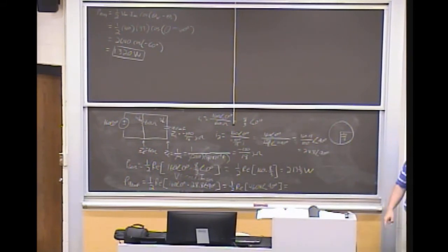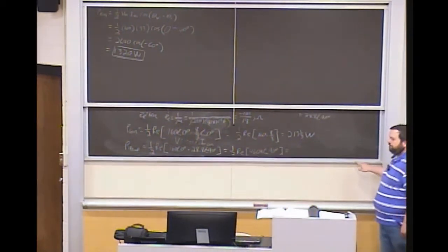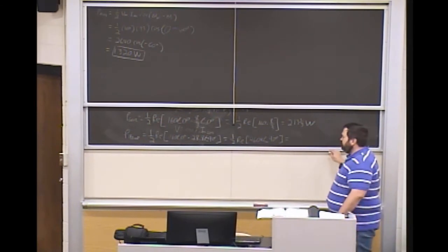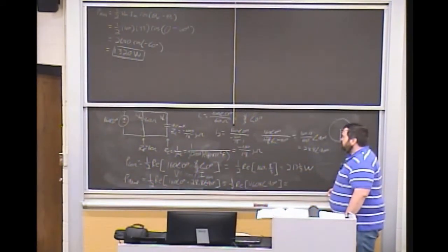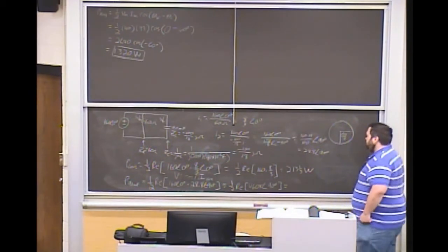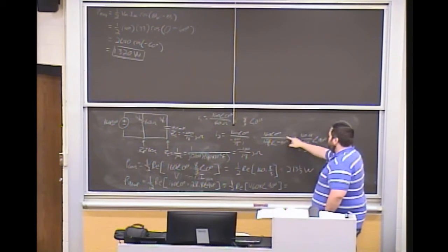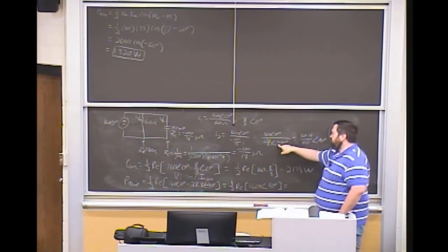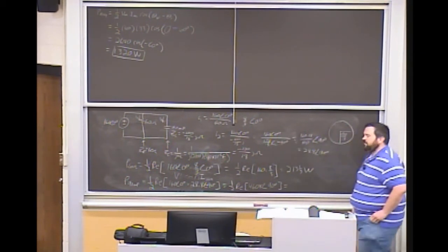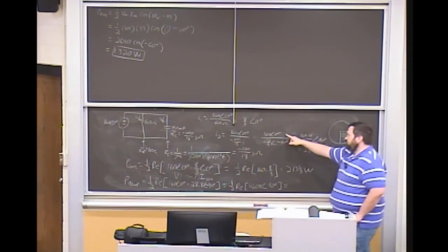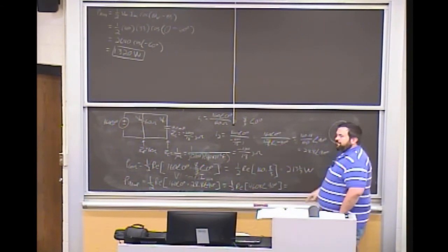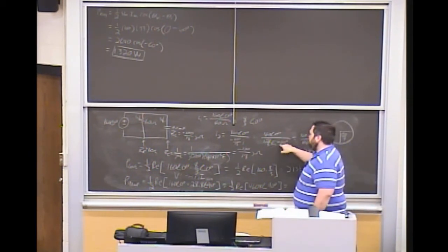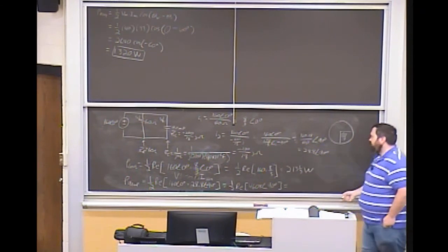Griffin, can you raise the board just a little bit? Yep. Thank you. Yep, James. Back up above where you had it as negative 90 before, how did you get from negative 90 to regular 90? Did you do a conjugate there? When I divide these, I end up subtracting. Right. This minus this, so 0 minus negative 90 becomes positive 90. This is my voltage. This is my 0 current. Minus, that makes sense. Okay. So I end up with a positive 90 because when you divide these two, you subtract the phase shifts. So that's how I got that.